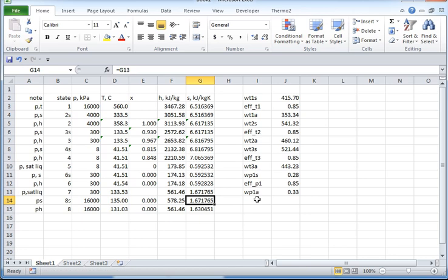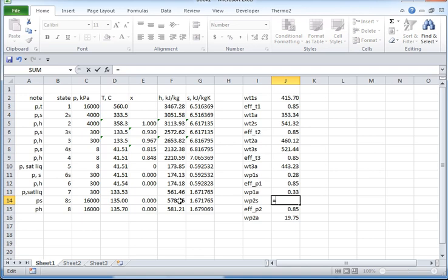So now I need to do the second pump, the efficiency on the second pump and the actual work of the second pump. Let's go clean up this. It's equal to going from state 7 to 8S, right? So 16.79 kilojoules per kilogram. It actually required this many, so this enthalpy is that H plus that. So we got the H there.